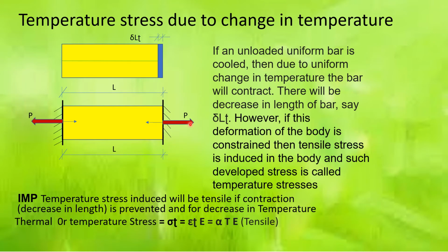Here it will be developed in the positive x direction. Here also the bar will try to come inside like this, but it is prevented, and a reactive force will be developed here in the negative x direction, and we can very well imagine that now these two forces are tensile.